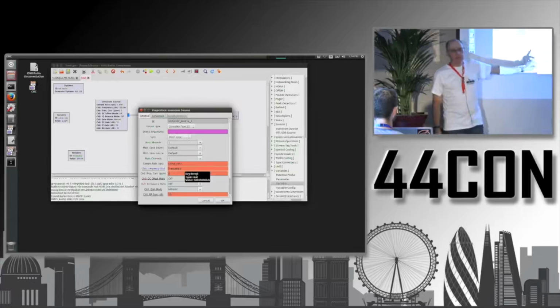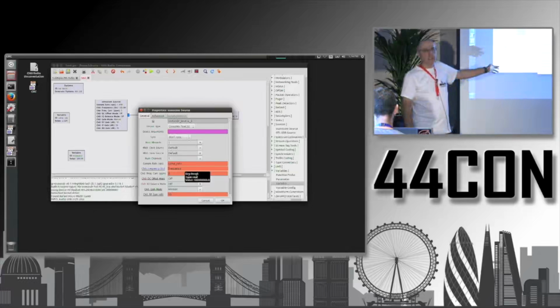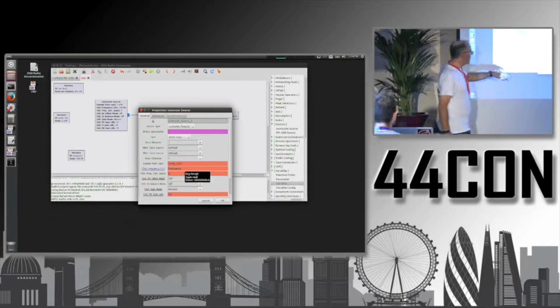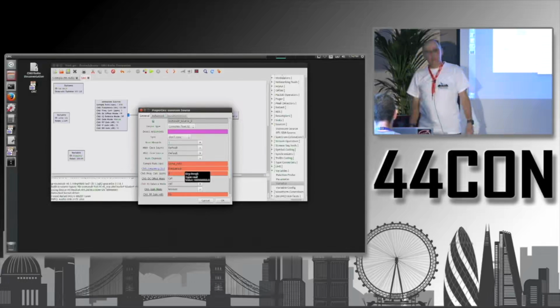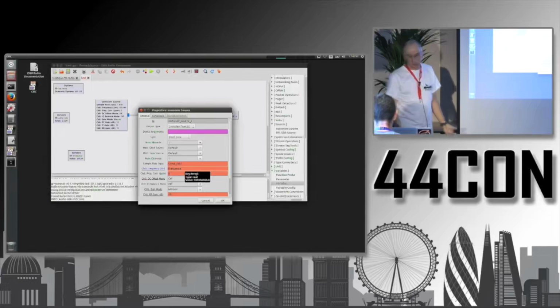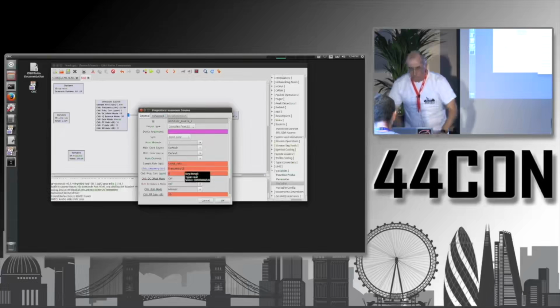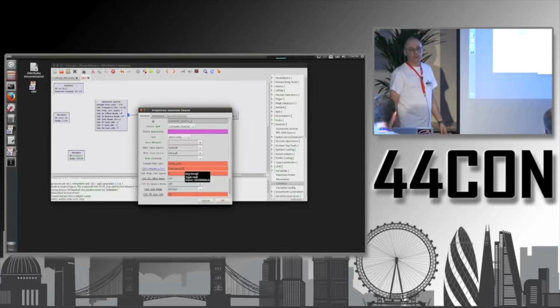Remember that I told you that GNU Radio Companion here is generating Python programs. So what you are typing here are actually Python expressions. So here just the name of a variable, but you can do different operations with it. For example, you would be able to do *2 to have the double of the frequency. That's not something useful here, but there are cases where you can do conversions.